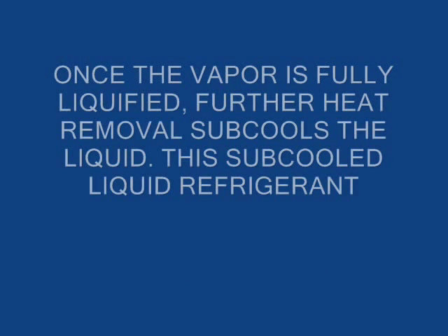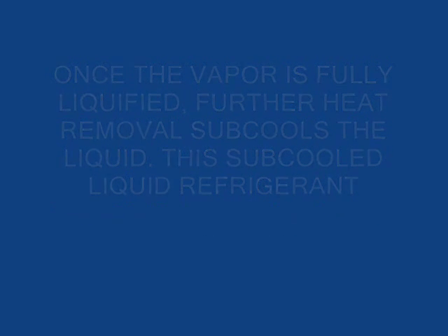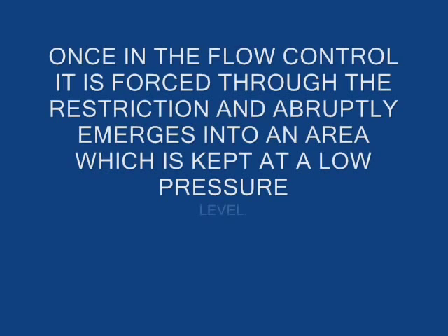Once the vapor is fully liquefied, further heat removal subcools the liquid. This subcooled liquid refrigerant then flows into the liquid line and on to the flow control. Once in the flow control, it is forced through the restriction and abruptly emerges into an area which is kept at a low pressure level.